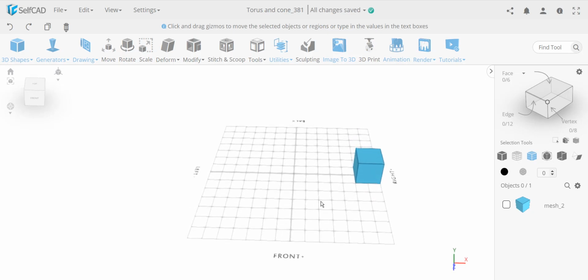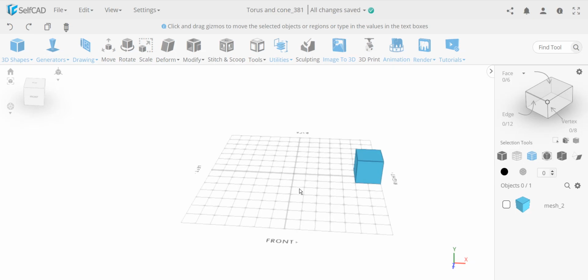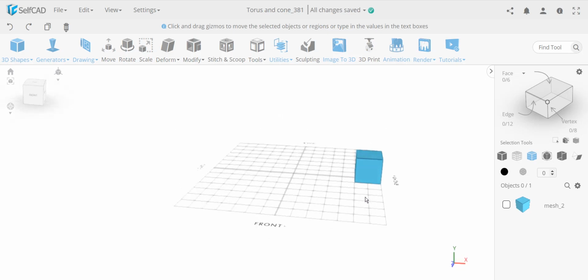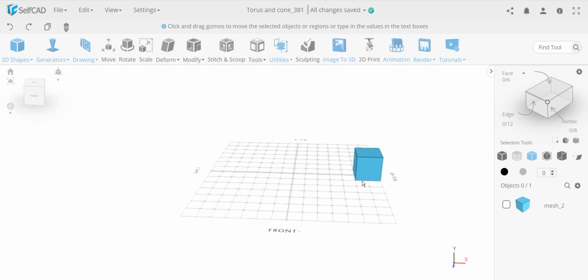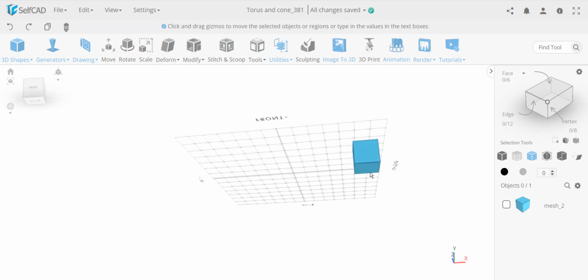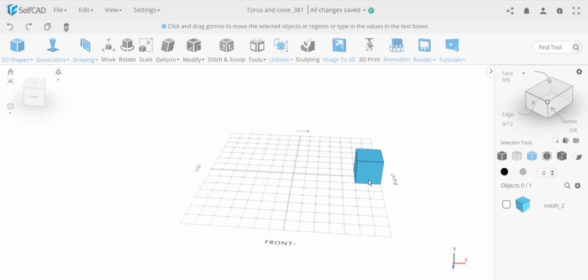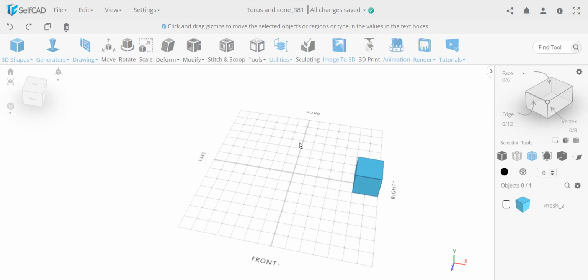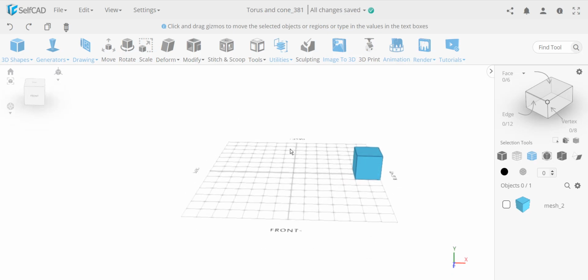And that's basically called the global coordinate system, which is the measurement from the scene, the coordinate system from the scene, so to speak. And then the object follows the same logic, and the pivot would be the center. More importantly, positioning a pivot does not necessarily mean changing global or local coordinates. What it means is that if I'm going to move it, using a gizmo, it will be aligned with the same thing. In this case, the X is this way, the Z is the depth, and the Y is the height, regardless of the angle of the object.